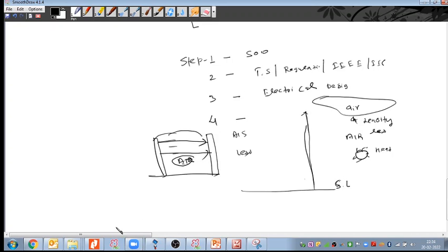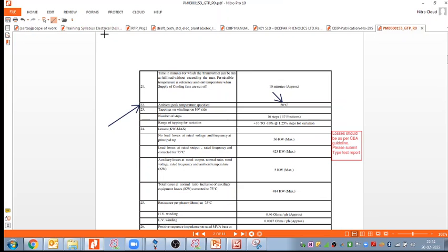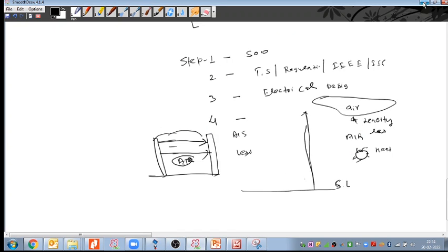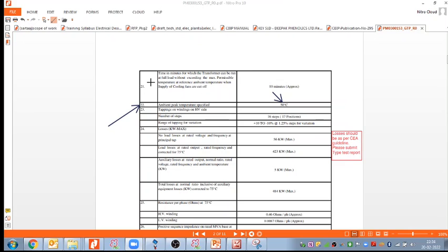So now we are done with this. GIS is not exposed to the environment, Silpa. So it will be less impacted compared to the AIS, and that is why in these kinds of installations, we go with the GIS, not the AIS. Yes, it will be less impacted in case of GIS because it is not connected with the outer environment.